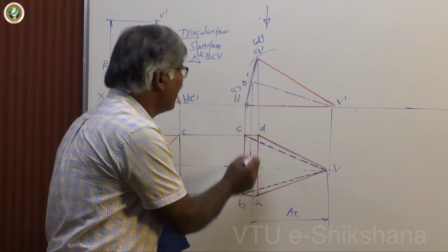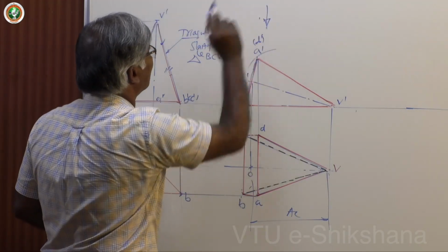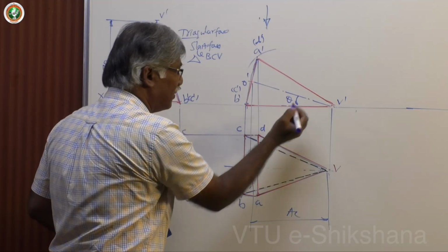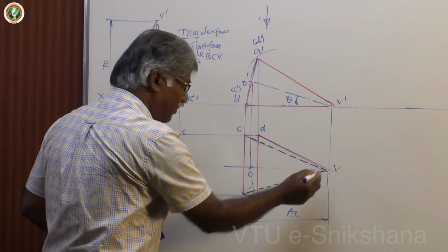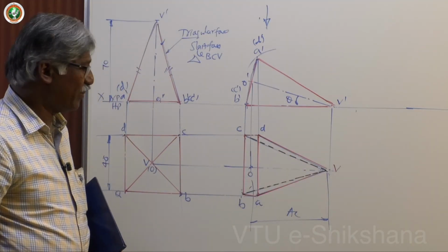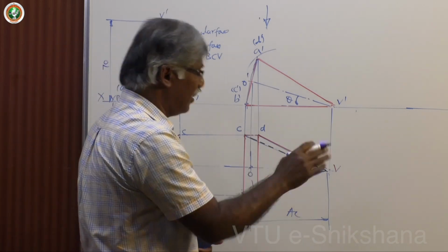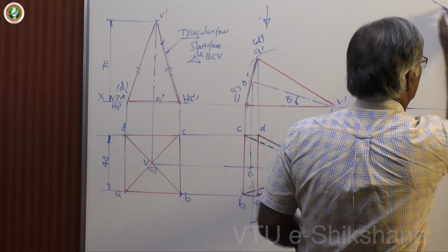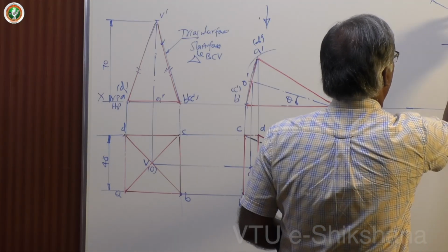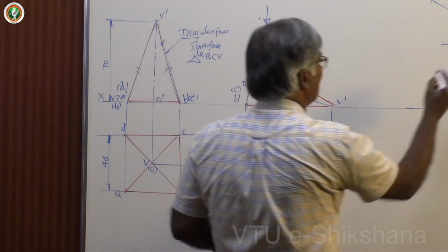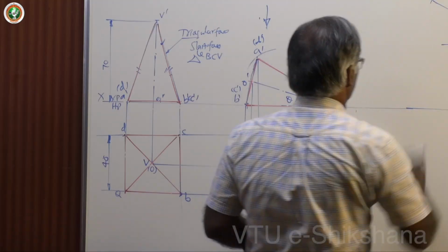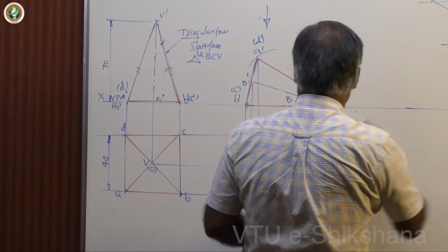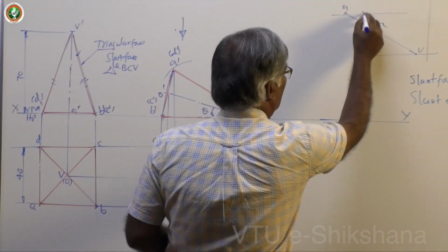Now, since he has given directly the axis inclined at 30 degrees to VP, already the axis is inclined at some angle theta, definitely this is the apparent length. Then you take the true length and apparent length separately, you can do better. So this is the true length of the line, axis VO1, then draw a line, then take the apparent length, mark.